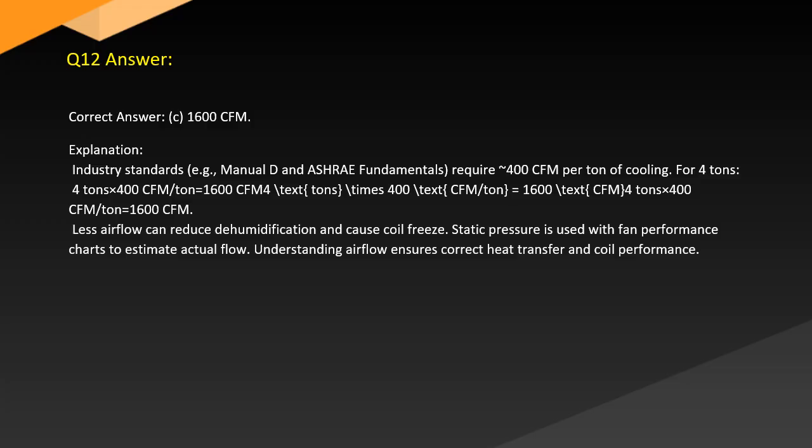Less airflow can reduce dehumidification and cause coil freeze. Static pressure is used with fan performance charts to estimate actual flow. Understanding airflow ensures correct heat transfer and coil performance.